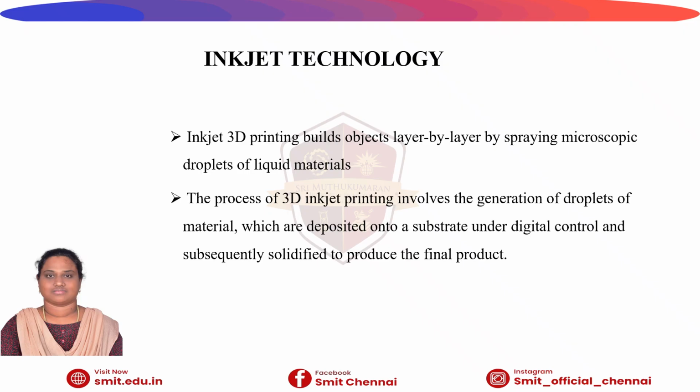Similar to conventional inkjet printing, the material is deposited only where required and it's solidified using UV light, heat or chemical bonding. This technology offers high resolution, smooth surface finish and the ability to print complex geometries, making it suitable for prototyping, medical models and full color parts.